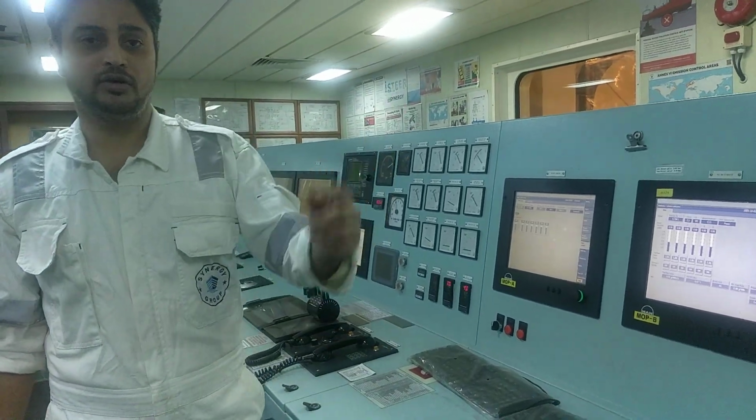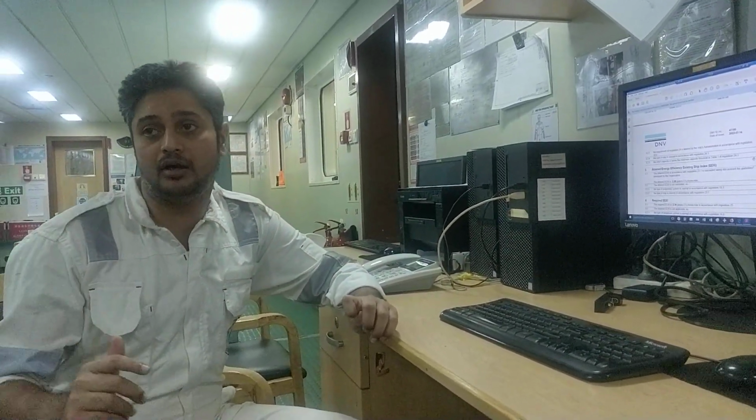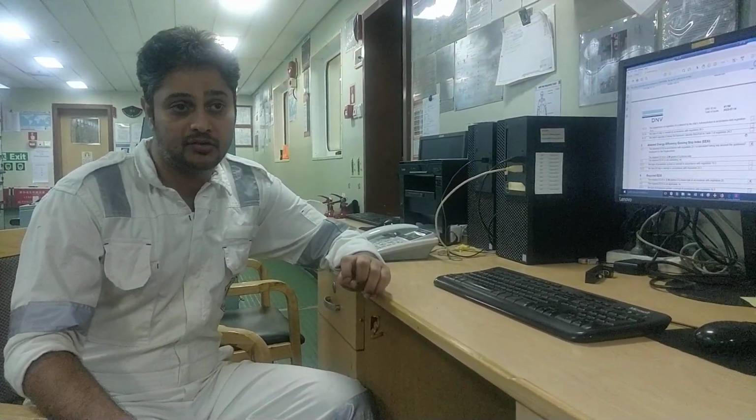So now I will show you the documentation involved. Regarding the documentation, if you have engine power limitation installed in your ship, there will be a new set of vessel maneuvering characteristics on the basis of the limited power, what the maneuvering characteristics are when you do bypass, and within restricted power. During pilot exchange also this has to be discussed.